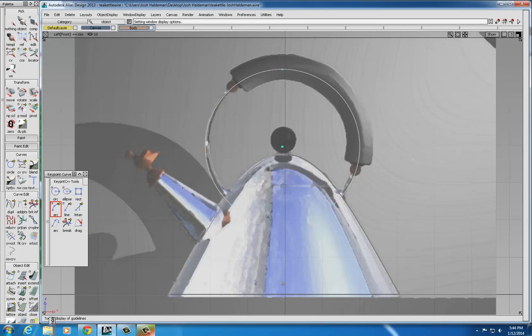Now that I've created the shape, you can see that I've got a little bit of a misalignment on the curve itself. It's okay on this side, it's okay right about here, but on the other side of the object, it extends out a little too far. You can fix that by dragging the key points that you've placed. That's using this drag key point tool. You can't pick CVs or edit points like you can with other things up in the pick menu, because they're not CV or edit points. They're key points in this case. So this is the only way you can pick them.